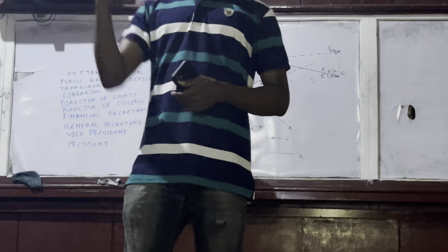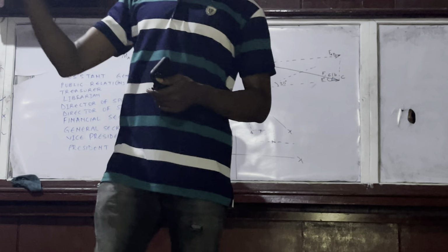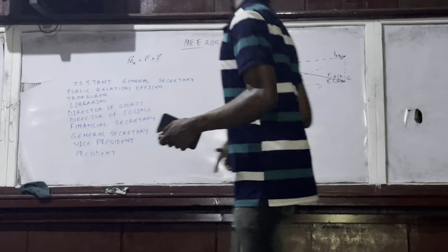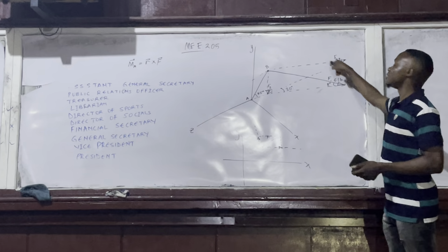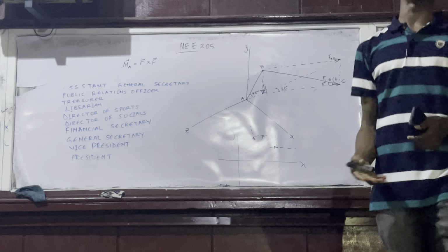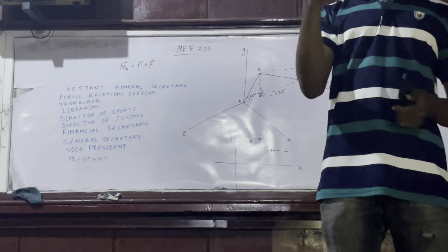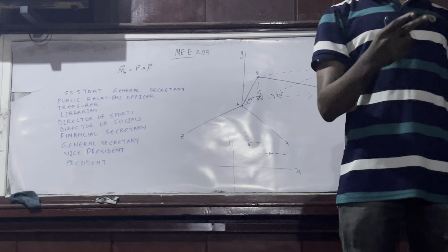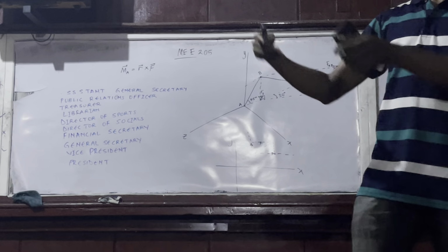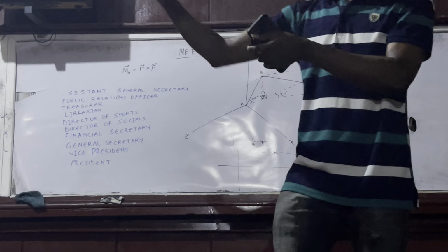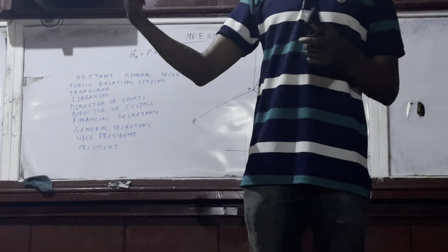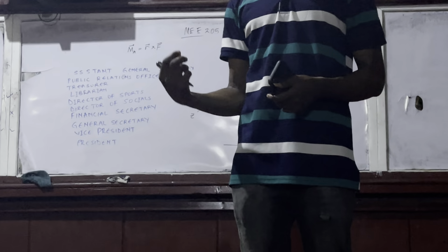So the next thing to do is the other component that is not along any of the axes. We will now resolve it in its own plane as well. Does that make sense? That means we identify the plane where this is. It is in the xz plane. So we now have to resolve it inside the xz plane. Altogether, like I said, a force can only have two components. So I've picked the original force I was given. I've resolved it into y component and xz component. The next thing to do is now that xz component, I'll further resolve it into x component and z component. Why? Because it is not along any of the x, y, z axis that I'm interested in yet. Is it making sense?